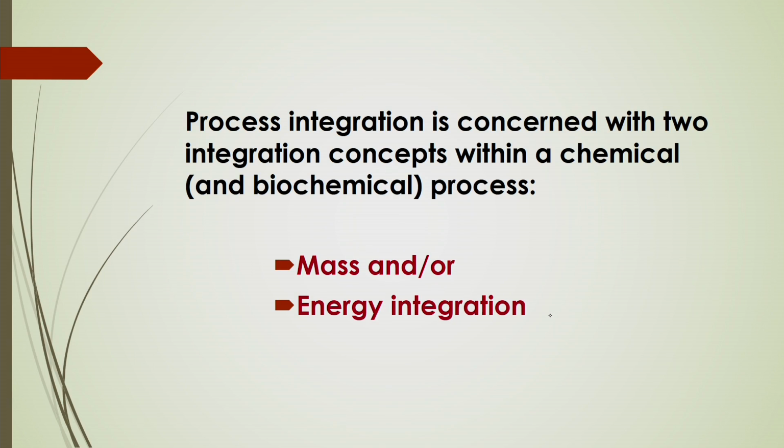In that case, through the center of the column gas is supplied, whereas adjacent to the wall the liquid will be falling down as a thin liquid. So, in that case there will be contact between gas and liquid, through which there will be a mass transfer. Now, in that case it is seen that for the overall volume of that gas-liquid mixture, the energy will be high, whereas you are getting less contact area.